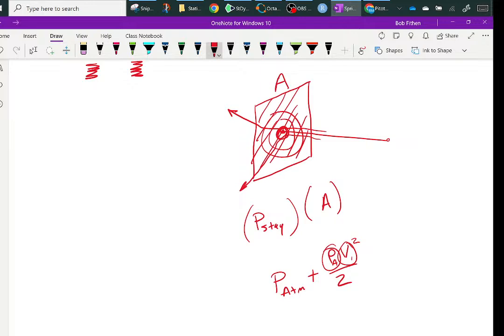That doesn't include any dynamic loads, because there could be shaking going on. But this was a structure that was very, very stiff, had low mass to it, and the frequency of vibration of the first mode was really high. So I did that calculation, and with that you probably have a factor of safety of 5 or 6.